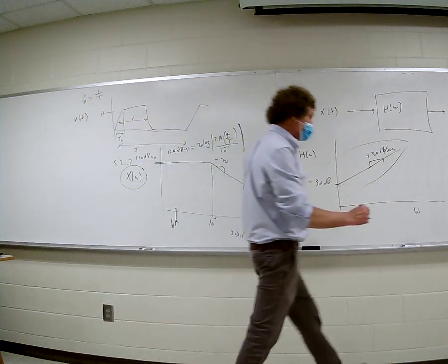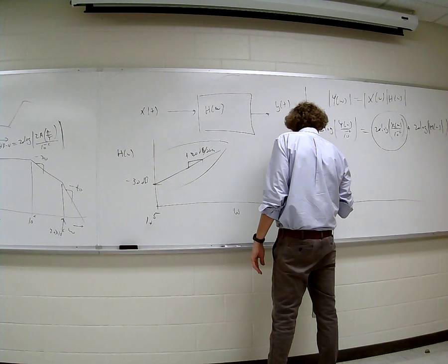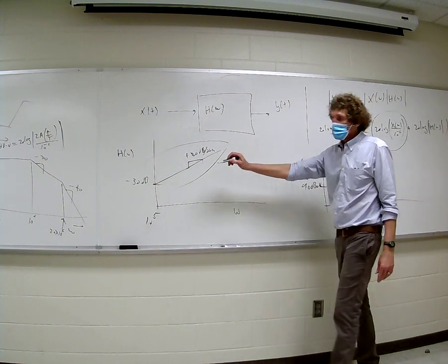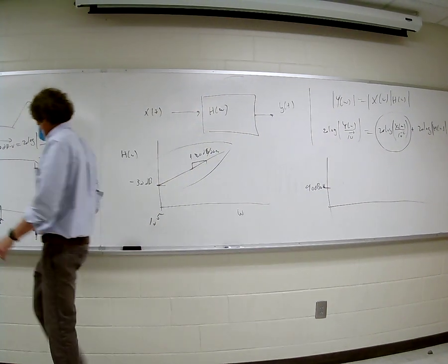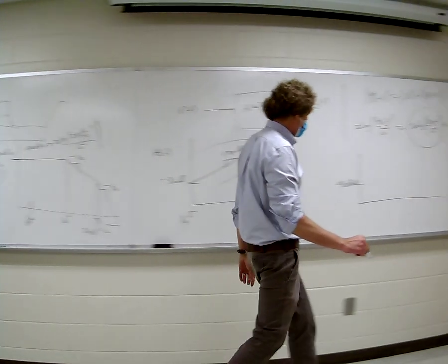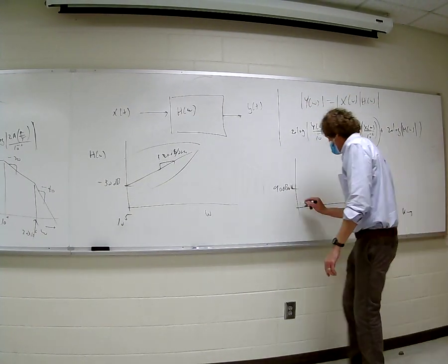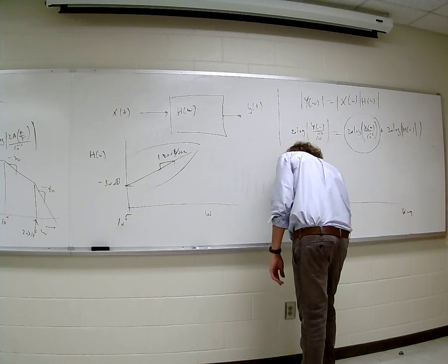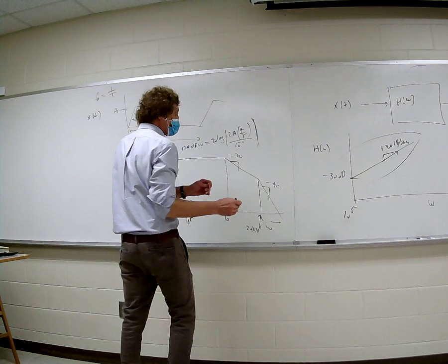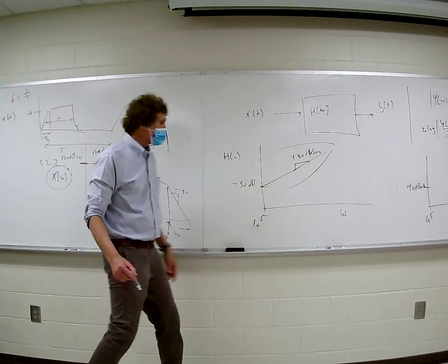This should be in there. So you start at 90 dB microvolts, right? And what's the rate of increase? 20 dB per decade. Now just watch. So it starts at 10 to the 5th is where my drawing is going to start. This is going to be versus omega, and this will be 10 to the 5th. I start right here, and I'm at 90 dB, and I'm going to go up at 20 dB per decade.